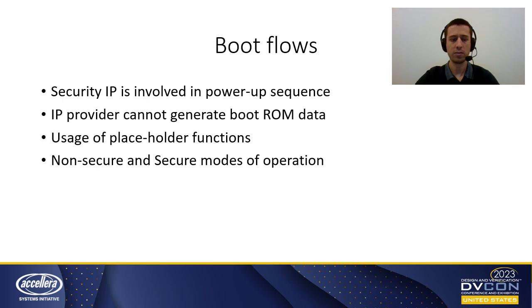Now when a security unit is available in the SoC, then it is usually also involved in this power up sequence, because in case a security unit is corrupted or compromised, we may not want to actually enable the system.